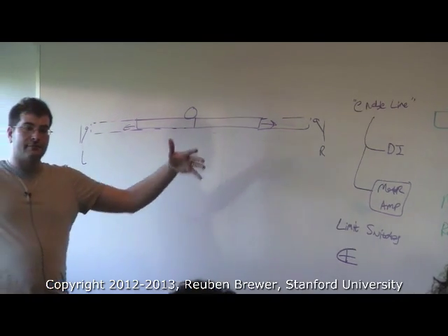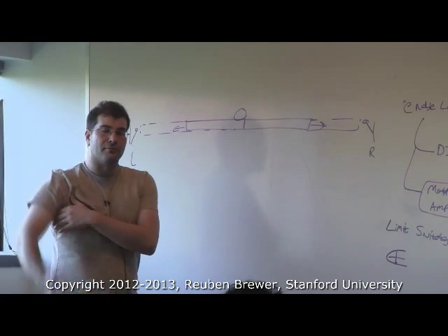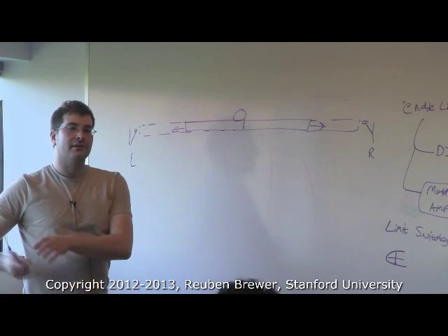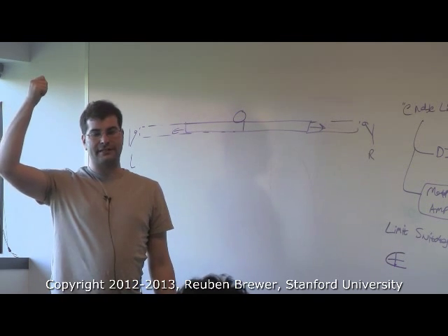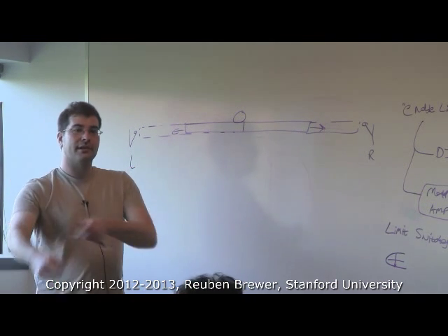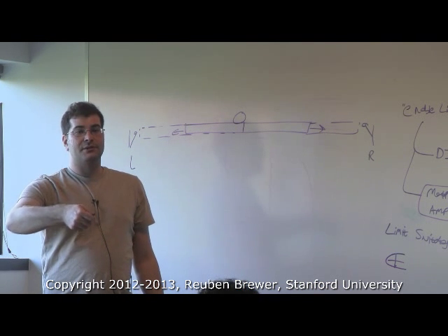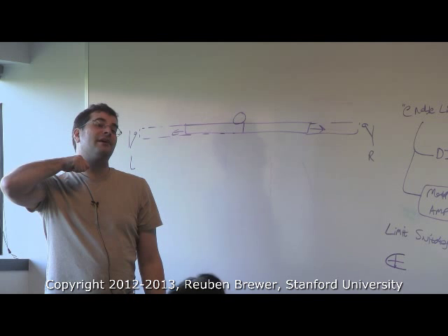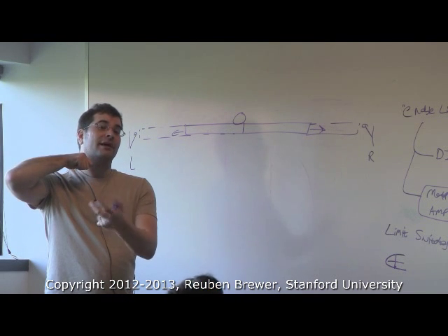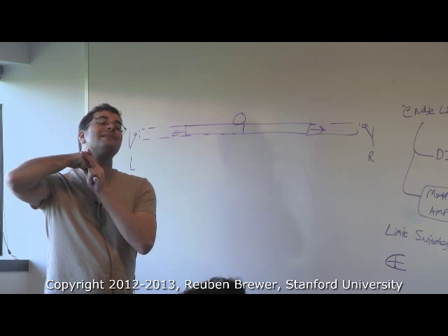Counterbalancing is if power goes down, say I have a robot arm wielding a knife, a sushi robot. When power shuts down, is it going to go crashing down? You don't want that. You would like a counterbalance so it just hovers. The other issue is backdrivability: if the knife is right here, it didn't cut me, but I'm a bit uncomfortable with this close of a shave, and I shut down power and it's counterbalanced, can I get it out?